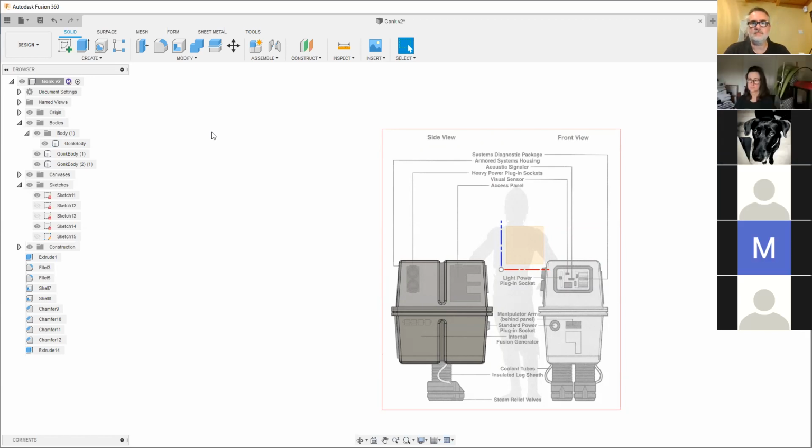So Michael, there's other things as well with the printer. You have your flow rate and your E-steps and all that stuff has to be really dialed in to get accurate hole and peg dimensions. Absolutely. And that's where, again, just through experience, I've got a bunch of tolerances that I tend to use. But if you put a 10 mil part into a 10 mil gap, there's no prints I've seen where it just slots in. You would still always have a little bit of a tolerance for it to move in there. As I said, between 0.2 to 0.35 is what I've seen on a number of 3D printing groups, and it tends to be what I use.